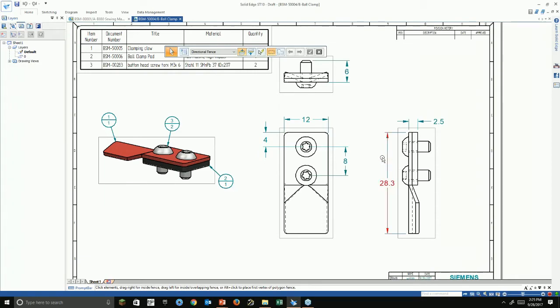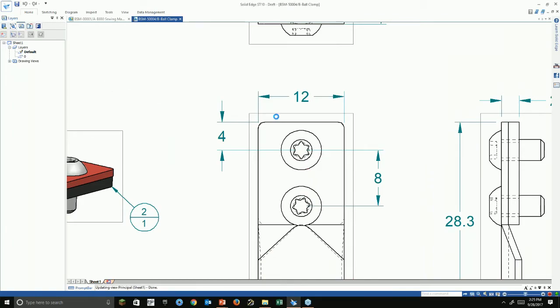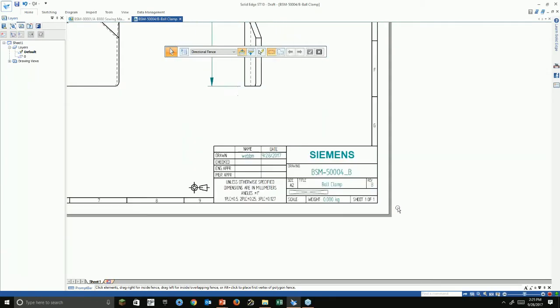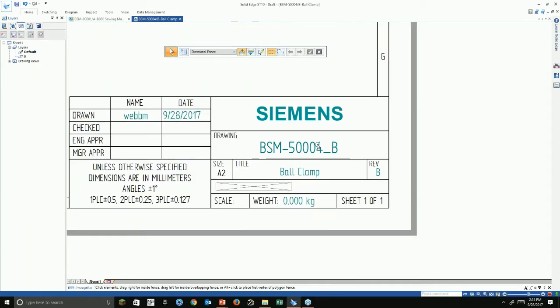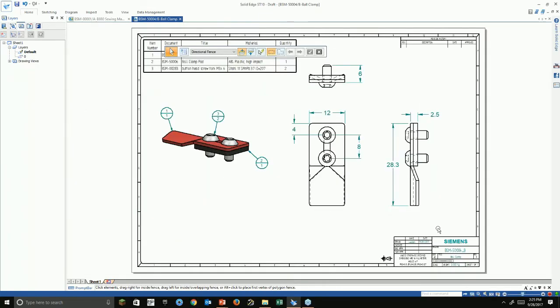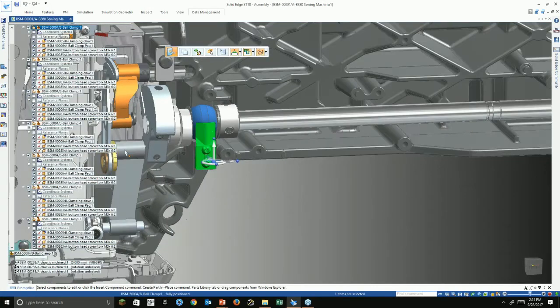Anytime you see boxes around your parts in Solid Edge, it's out of date. And obviously, it's the old version, so let me update my draft to the new release. All right, so there's the new version. There's the Rev B, so it automatically keeps track of that, just based through properties again. All right, so that part's ready to go. It's released. Draft's done. Looks good.